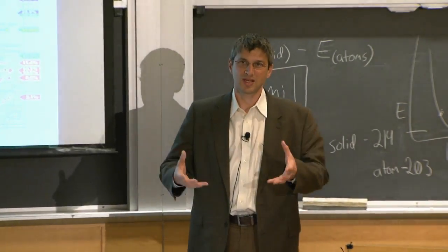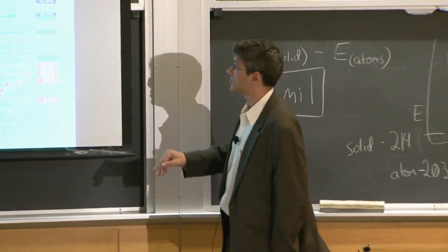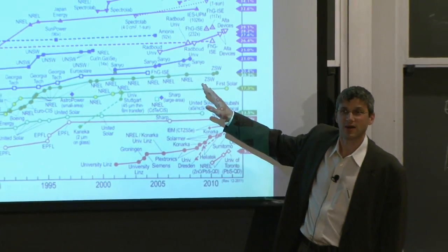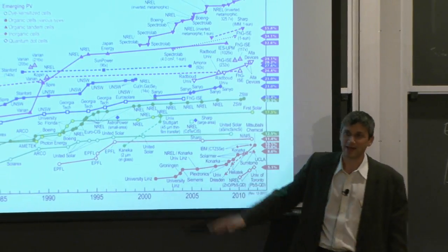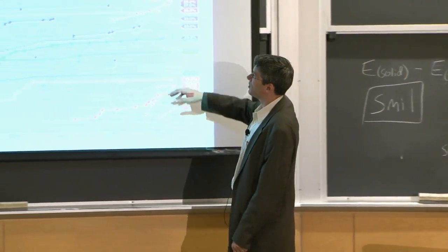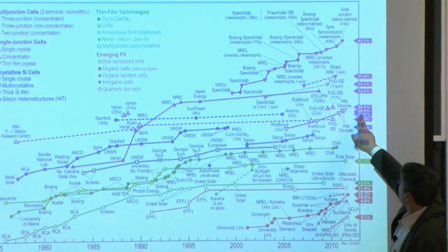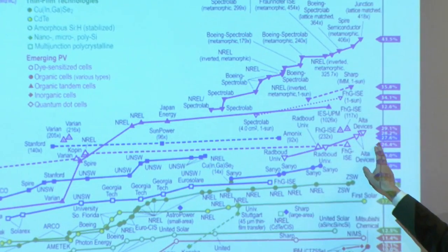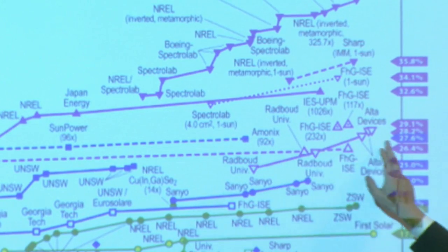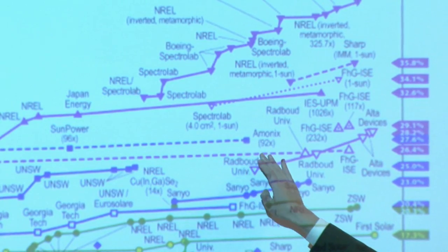So these are sort of the efficiency that you could get at most. And then there's what you can actually get in your product, right? And there's a big difference. These are what the record has been in research labs, tested and verified by NREL. And then there's, now I buy it. Who can sell me it? And what's your efficiency? And it's always lower. And for monocrystalline silicon, which is the best you can do, that's here, you see that we're pushing what I'll show you is close to the theoretical limit of how efficient this process can be. But that's 27%, you see. But if I buy it, 18% is the best you can get on the market of monocrystalline, right?